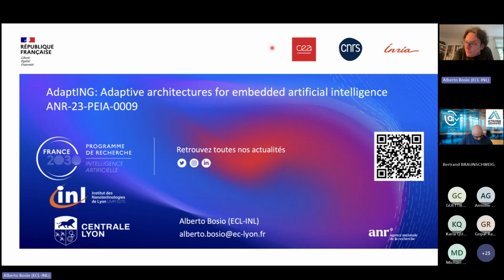So what you can do is, if you are able to do this dependability evaluation, you can understand what are really the critical components. You can only triplicate those specific elements, for example some neurons, some layers, so you don't have to triplicate the complete system, but you can really do something focused on your application.